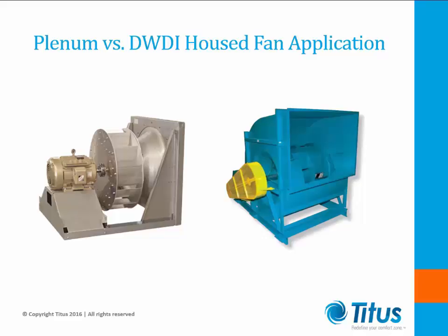the housed fan. Also, since a Plenum fan has no scroll, it typically means larger fans can be installed in the same size cabinet compared to the double-wide double-inlet fans, which generally produces better sound characteristics in those applications. For design pressures at or below 6 inches water column, it is very common to see supply air sound power levels lower when using a Plenum fan instead of a double-wide housed fan. Additionally, perforated liners may be used in Plenum fan sections for greater attenuation.